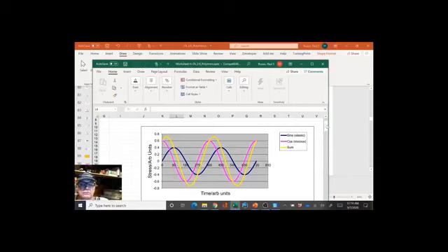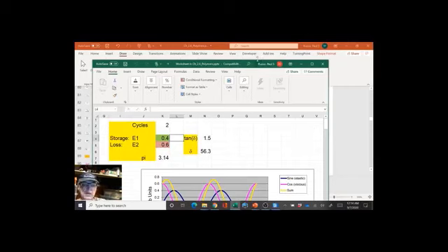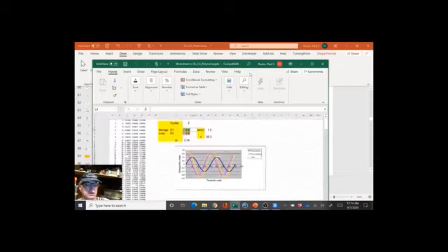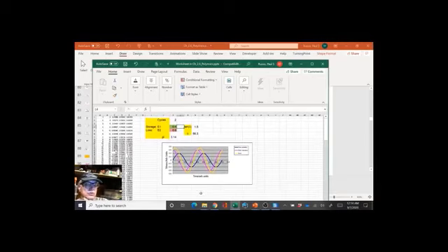So I think if I am smart enough, I may be able to shrink this down to where we can have some fun and change some numbers around. That was 40% elastic, 40% storage, and 60% loss. So I'm only going to change the elastic component, which is 0.4. I'm going to change that to 0.85, just for the sake of argument. So that means there'll be 85% elastic and 15% lossy viscous motion.